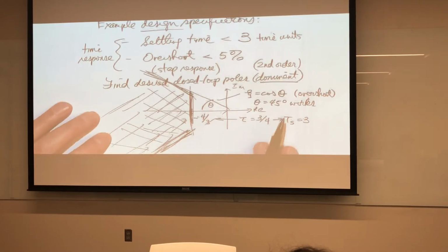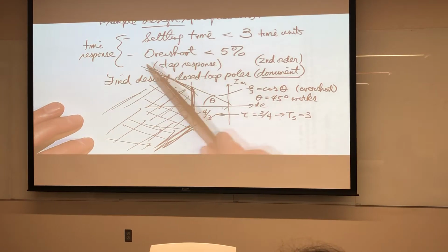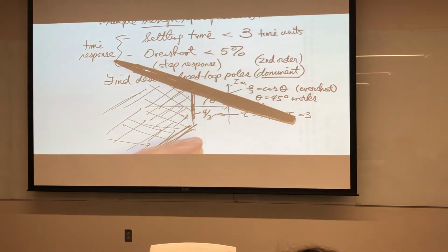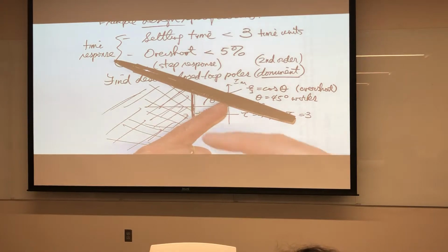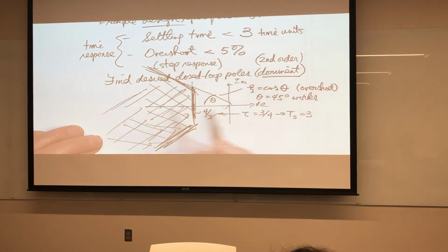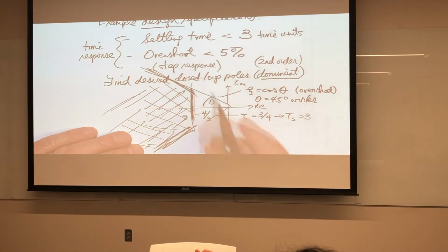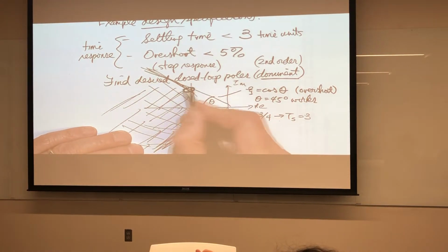We need to keep our poles to the left of where my pen is right now, and I need to keep my poles inside this sector right here, and the intersection of those is this shape right here. Okay. So we need to pick a point out here. So this is minus 4/3. Let's just pick this point right there.